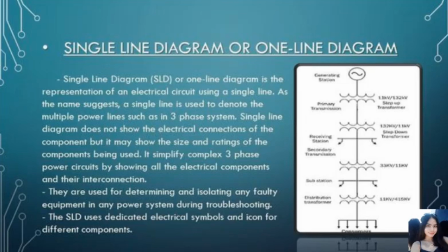It simplifies complex three-phase power circuits by showing all the electrical components and their interconnection. They are used for determining and isolating any faulty equipment in any power system during troubleshooting. The SLD uses dedicated electrical symbols and icons for different components.